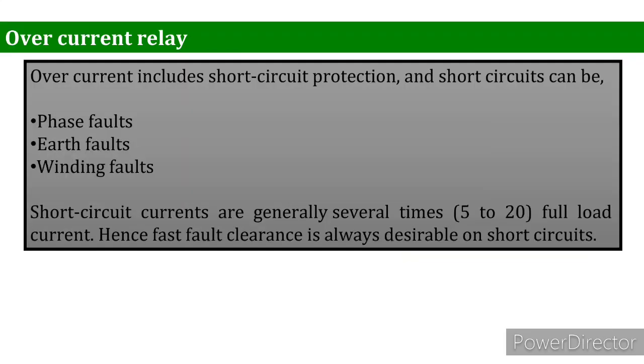Well, as we mentioned the overcurrent relay basic definition in the last slide, we must say that overcurrent protection protects the electrical power system against excessive current, which is caused by short circuits and ground faults. Overcurrent relays can be used to protect practically any power system element, that can be transmission lines, transformers, generators, or motors.